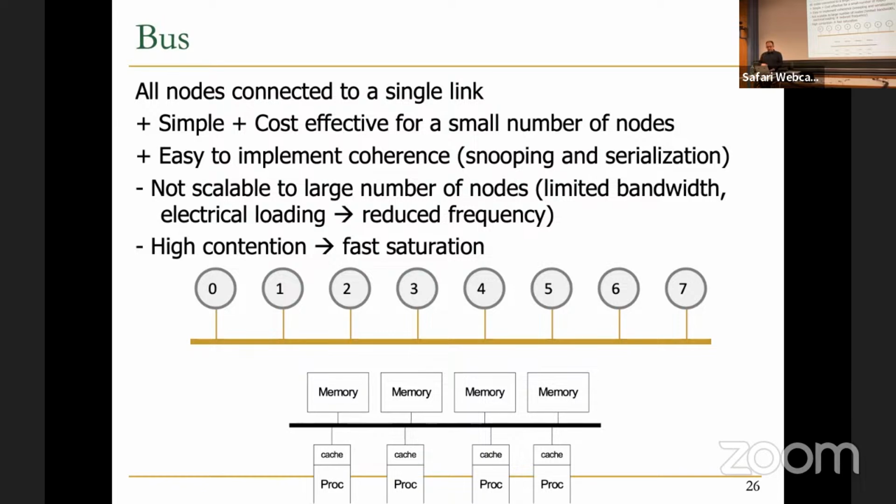That's why bus is very good for broadcasting and multicasting, but only 1 node can drive the bus. So when you want to write to the bus, you need to consult the arbitration unit. And when you have many nodes, your chance to get the permission to access the bus is getting lower and lower. And in the end, your performance is low.